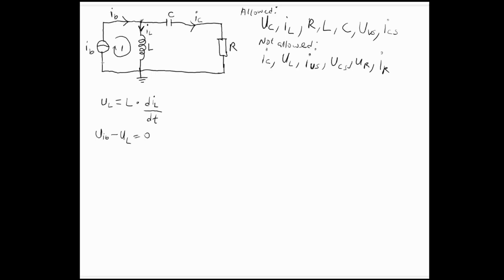So current sources also have voltage across them, but the voltage across a current source varies, it's not constant, because current is constant. So voltage depends on the load. That's why it's a current source. But in voltage sources, the voltage is constant, but the current depends on the load, right? So let's move on. We cannot use mesh 1 alone. It's not sufficient because it has very few variables. So let us try mesh 2.